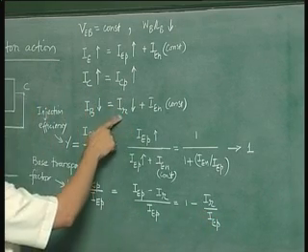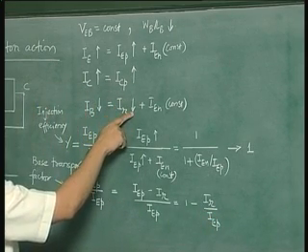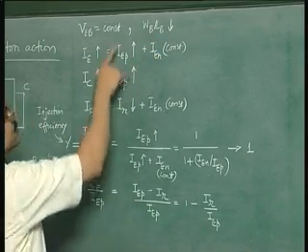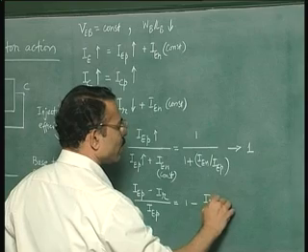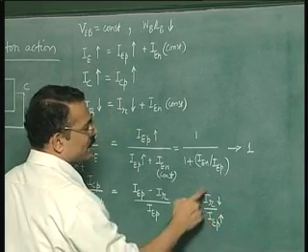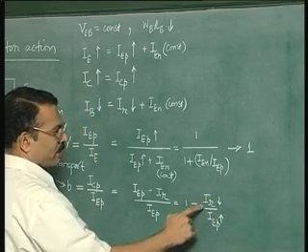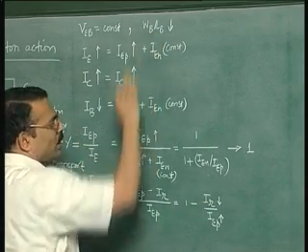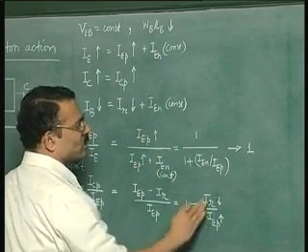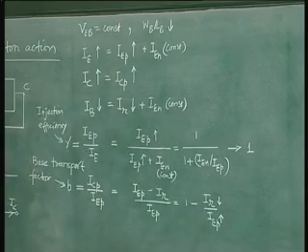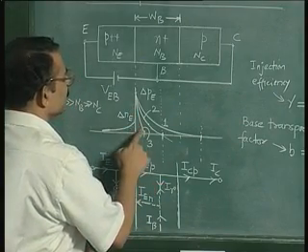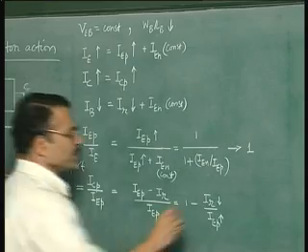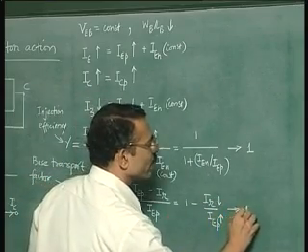Now as shown here, IR is already falling as WB by LB is reduced, and IEP is increasing. So this is falling and this is increasing. So obviously this ratio goes on falling, and in the limit of WB by LB very small, in fact this ratio will become almost 0. The recombination current here, which is dependent on the area under this curve, that is this area, will almost become negligible. So this factor also will tend to 1.